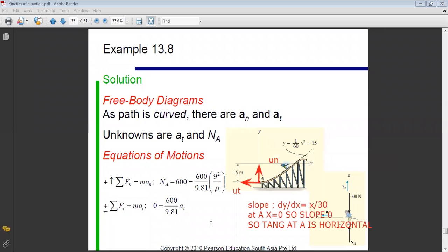And for UB, UB is perpendicular, and I will not need UB here. Why? UB is only needed if I have forces along UB, but as in the previous problem, here there are no forces along UB, so I will not use the equation sum of forces along B equals 0. But I can just present it, so this is vector UB.